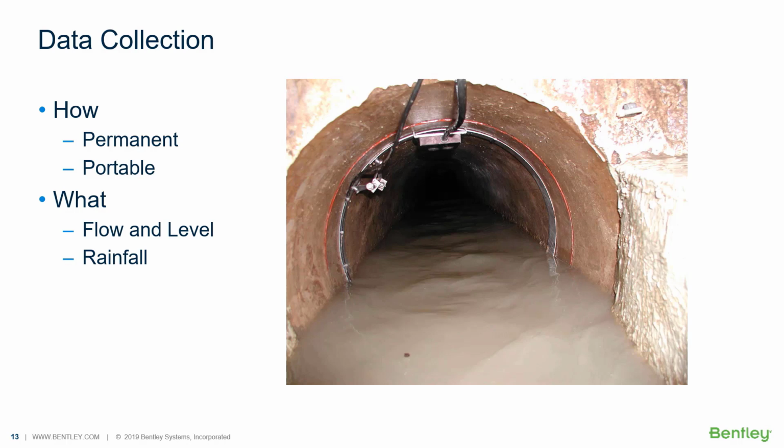So these are the ones you're generally going to have to do something about. That's not going to be enough available off the shelf. So let's look at some simple things you can do. This is now the real quick and dirty old-fashioned kind of stuff. You want to know what the flow is into a wet well? Well, you turn the pump off and see how long it takes to fill at a certain level.